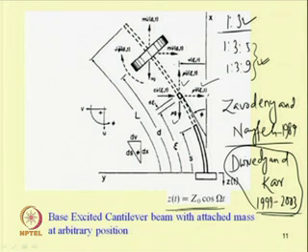So, we have taken this transverse deflection to be v and this axial direction deflection to be u. So, in x direction it is rho u double dot and in y direction it is rho v double dot. So, these are the inertia forces, and including the damping force, this is C v dot.